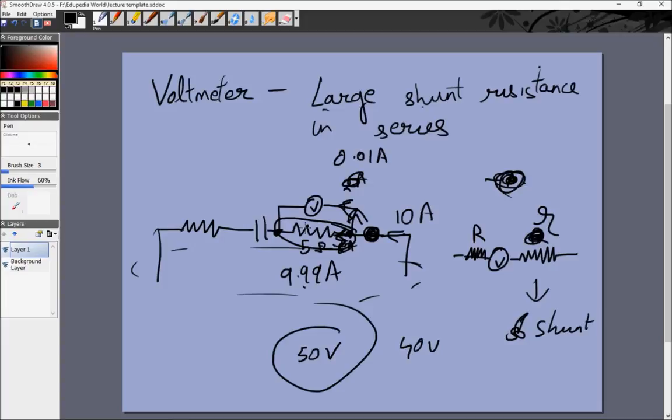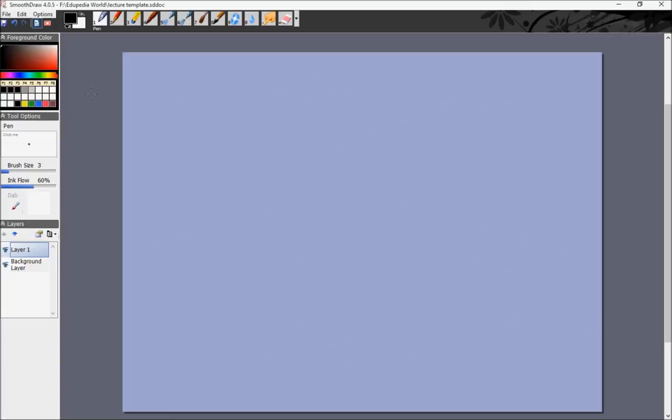So there's another type of device called a potentiometer, in which the value is completely accurate because we're not actually absorbing any amount of current from the circuit. We are creating a second circuit, our own circuit, and attaching it to the first circuit and applying our own batteries and our own resistances. So we'll not be taking anything from the circuit, hence the value will be 100% accurate. And that device is called a potentiometer, and it uses the concept of a Wheatstone bridge, which is what we learned right in the beginning of this video. So let's look at a potentiometer.